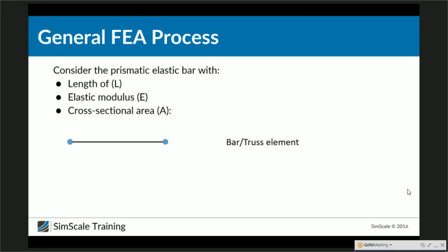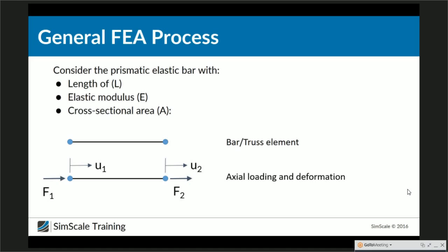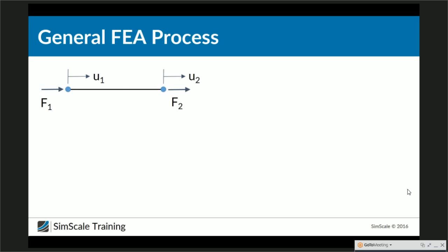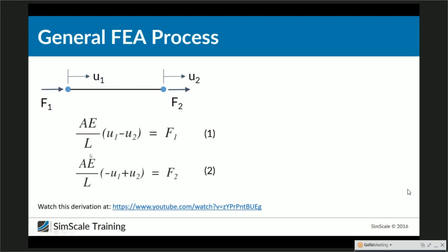On both cases, we'll take a look at the beam structure. On the top, you can see the analytical version of a beam. I'm quite sure you did something similar to this at school. And below, you can find a finite element representation of this beam structure. As you know, for this kind of beams, there are already analytical equations and solutions which you can use to calculate stress distribution, displacement, etc. But if we take a finite element representation, we will represent this elastic bar, this beam, by small bar elements like here.